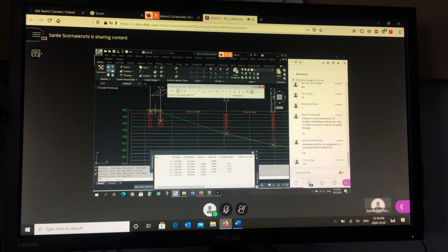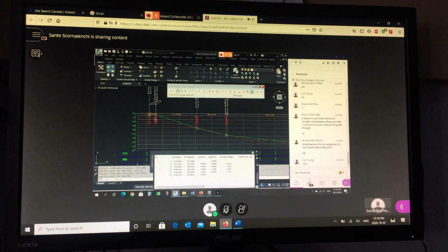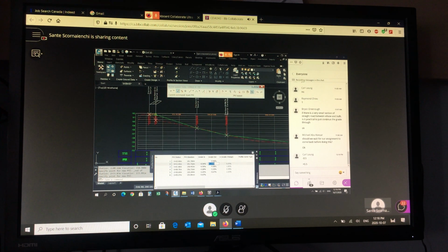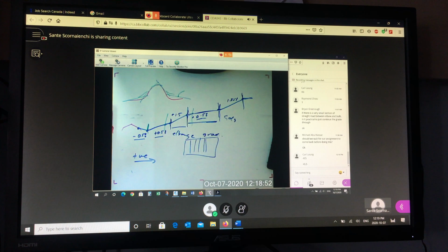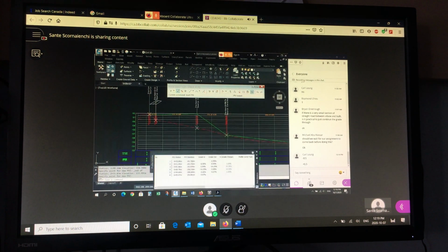So there's my low point right there. What's the next one? Positive 0.5. You don't need the plus sign, so 0.5. So there's my first stretch, 0.5% up to where the elbow starts. Then the slope in the elbow. Remember the slope in the elbow right there. Back to the grid. Slope in the elbow is positive 1.5. And notice the grid is adjusting because I'm adding data that's higher than the limit that I had before.